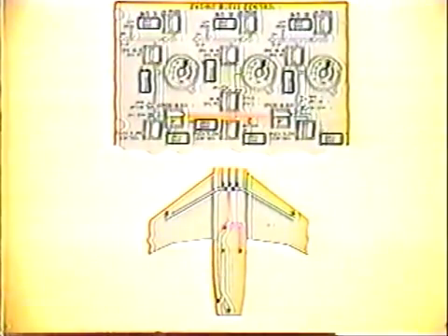The valves discussed so far can be seen on the panel and on the plan view. Note that the blue color code represents the ducting from engines 1 and 3 to the cross-bleed manifold. Green indicates the duct from number 2 engine, while the cross-bleed manifold is colored in red.